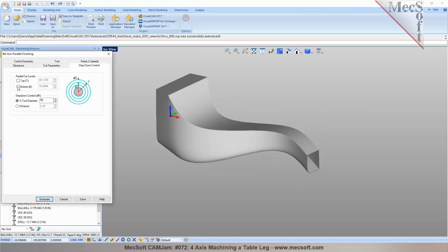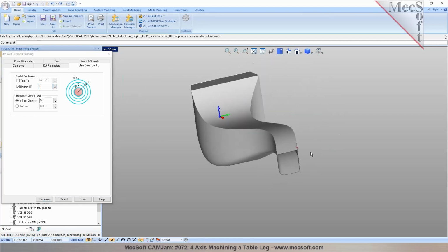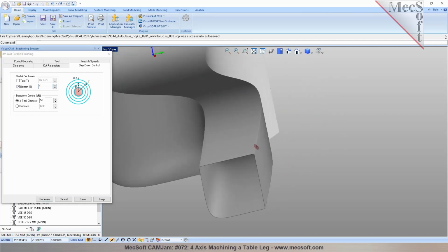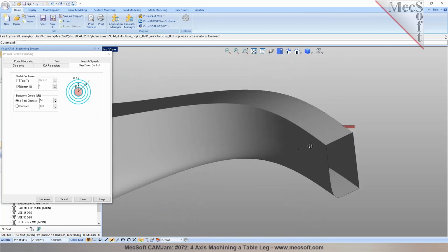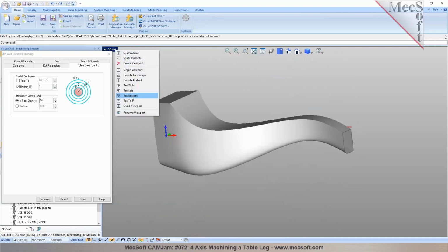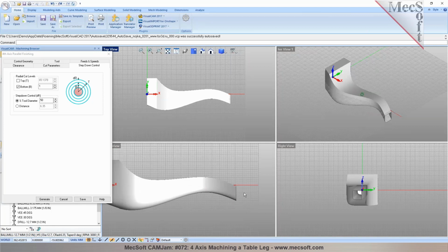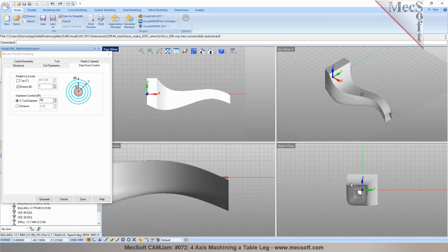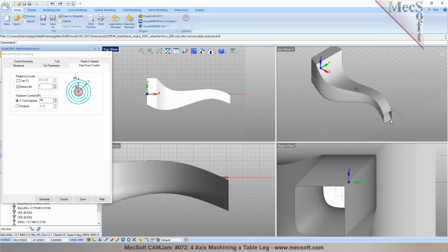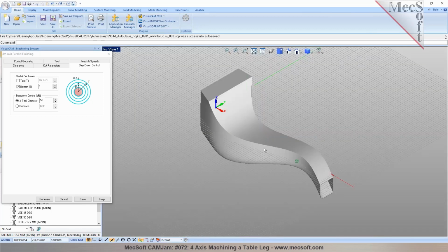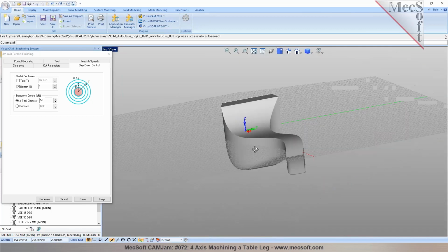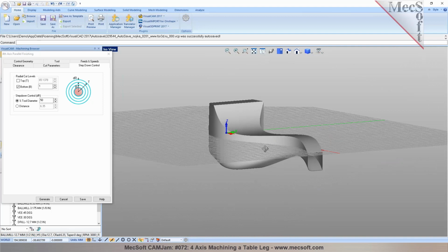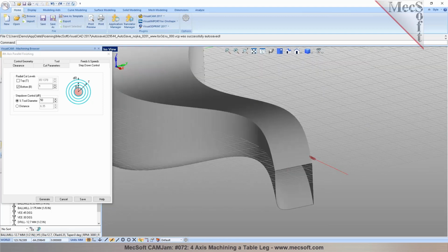So if you have features that are dipping below the rotation center, I could say do not go below, like, 1 millimeter or half a millimeter below the rotation center. So you can see that there's a small portion of this stock that's dipping below the rotation center. If you draw a center line, you will notice that there's a small portion that dips below the rotation center, right? Okay. So you can adjust the part and the stock part slightly to be above the rotation center, but if there are features, then you want to avoid that.